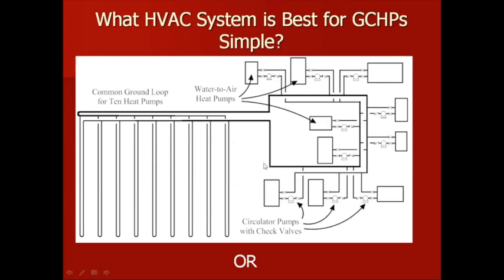We do have open loop systems in surface water, but you have to be real careful there because if you're in heating, in all but a few locations, the exit temperature of the water leaving the heat exchanger will be close to freezing.